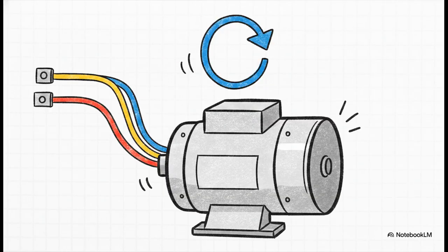If you guessed a swapped wire, you hit the nail on the head. Remember our fixed rotation order? A, then B, then C. If an installer accidentally swaps any two of those three-phase conductors during termination, it completely reverses the phase sequence. The motor just follows the sequence it's given, which causes it to spin backward. Fortunately, it's a super quick 5-minute fix once you know what phase sequence actually controls. You just swap any two phases back, and the rotation instantly corrects itself.